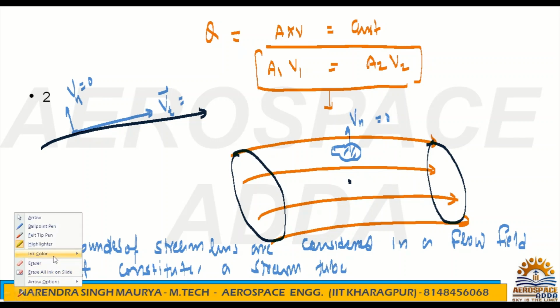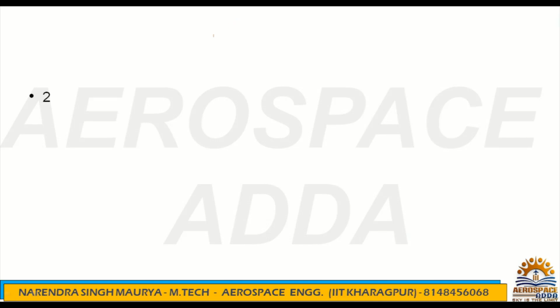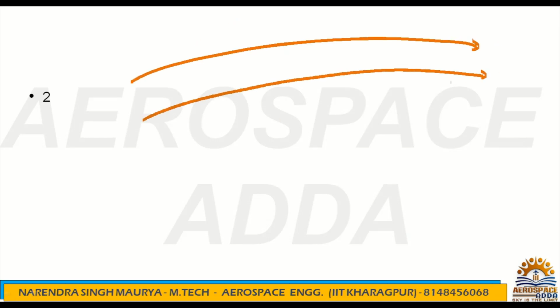So always remember, and when this tube is possible, what does it mean? Because everywhere the streamlines are parallel to each other. If I draw the streamlines, even if I'm drawing them curved, the curves will maintain equidistance. That means they are parallel. If they are parallel, they are not going to cross each other. That's the meaning of it. Okay. So the streamlines are everywhere parallel to the local velocity. Fluid cannot cross the streamline. I'm saying it again and again because this is a very important property.